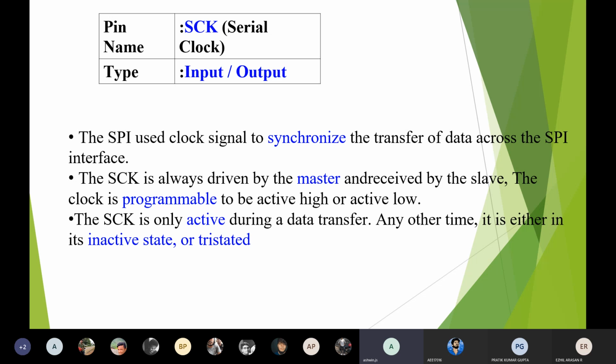This also makes the tri-state. You know one state is 0 and another is 1. The third state is nothing but high impedance. So the line is not connected to the ground, and it is not shorted with the 1, which represents high voltage, or with the 0, which represents the ground. It will be an open circuit, and an open circuit represents a high impedance state.